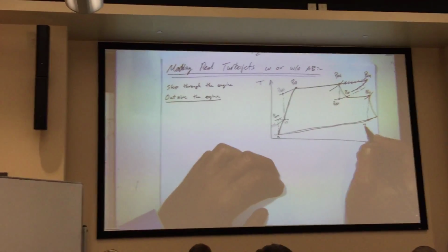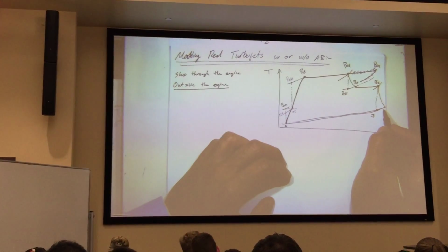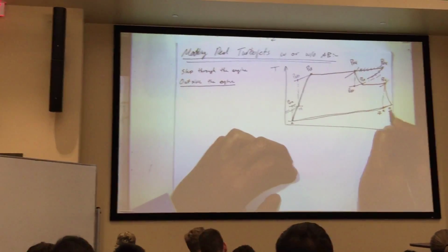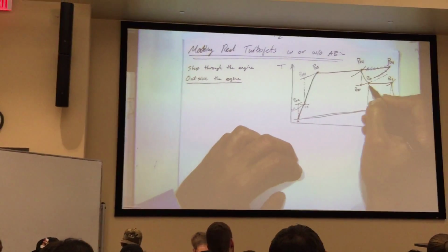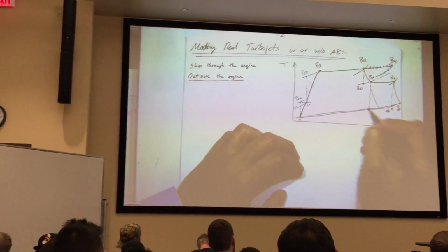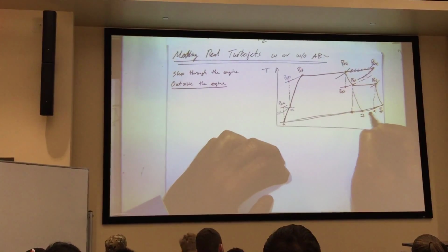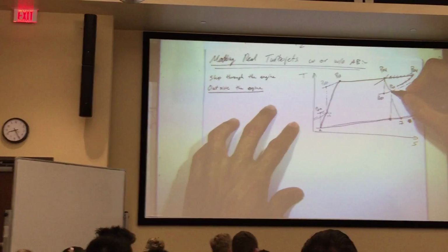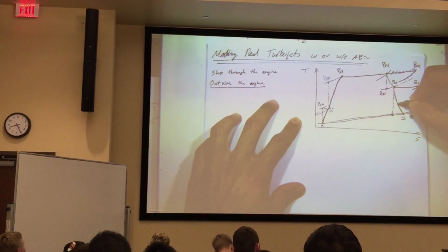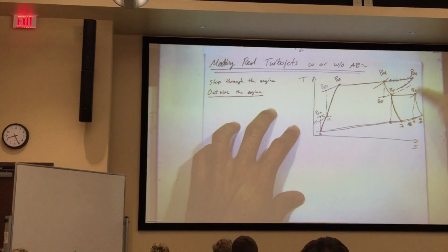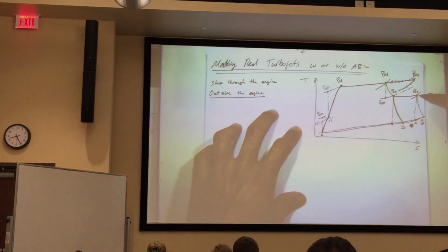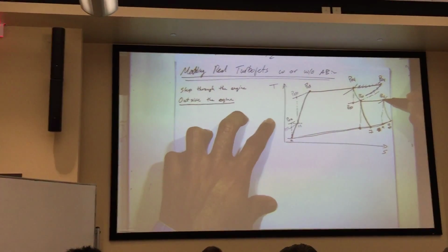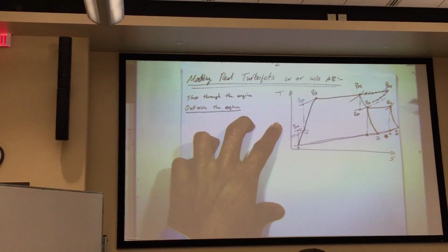So this is 7 versus, I'm sorry, this is ambient versus 7 AB, and we could make one without the afterburner right here. This is again ambient, and this is 7. So I have two situations where I have the afterburner right here, and the curve comes this way for the real turbojet. But if I turn the AB on, then I'm adding heat at a different pressure level. It's constant pressure burning, but at the same time I have pressure losses, so my ignition pressure is slightly lower. And from there, I have another curve that comes this way.